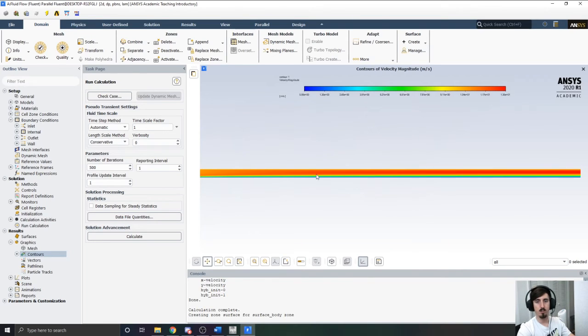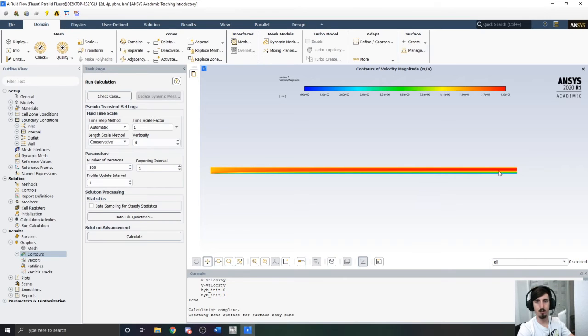So with the initial velocity being 10 meters a second and the top plate moving at 10 meters a second, we should experience a faster flow. But when it starts, it should be close to that 10 meters a second because that's what it's coming in at. And you can see at the end, it starts to reach that maximum velocity. Or, I mean, it starts somewhere around a third of the rectangular cross section. But we know that it's a fully developed flow, hopefully, at the end.